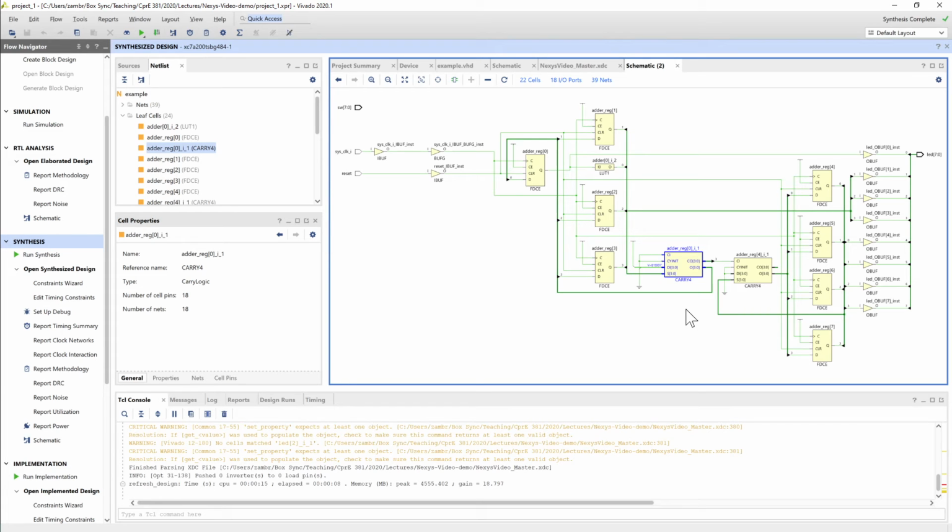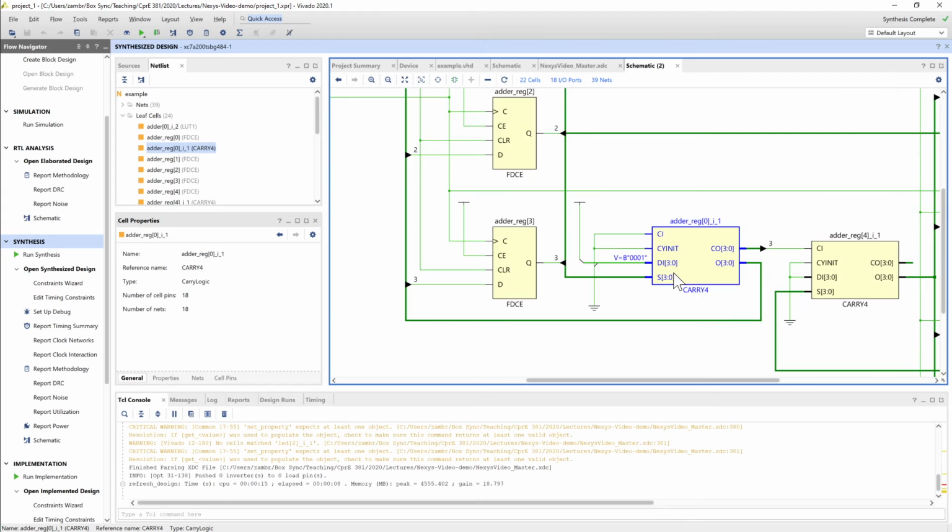If we get a chance, we'll talk about carry look-ahead adders that basically try to do 4-bit addition all in one go, and that's very likely what's being implemented. So that's 4 bits of the addition. I don't know if you can see that, but that's a 4-bit adder. It's not magic, right? Carry in, carry out, data out, sum. There's the other 4 bits of addition here. I wouldn't have named it that, but this is Xilinx's tool. This is their way of doing things.